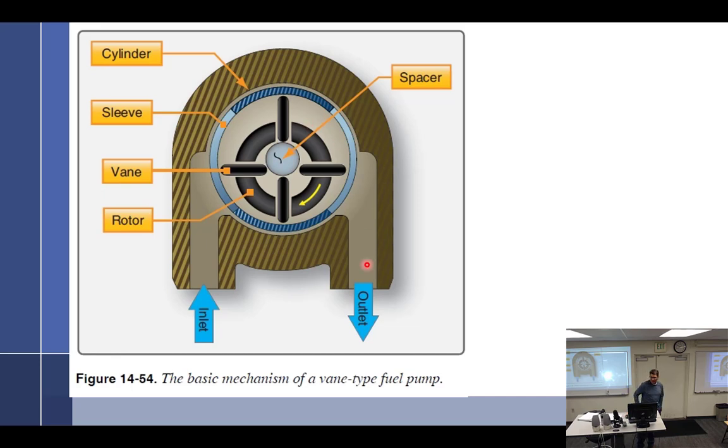How much pressure can you get out of this? Or how much pressure would you have? None right now. Why? Well, because it's a drawing. There's no restriction. You've got to have a restriction to get pressure. So if I put a pressure gauge right here, tied it off, picked it up right out of there, it would say 0 because there's nothing backing it up to create pressure.